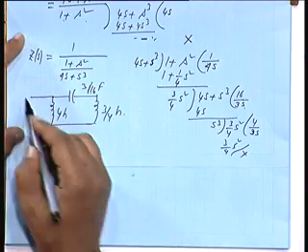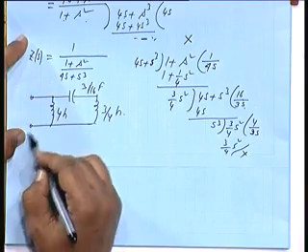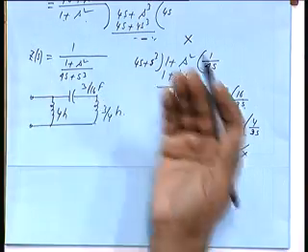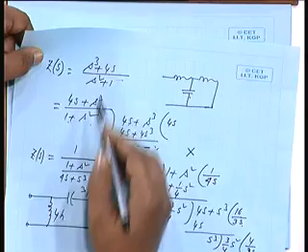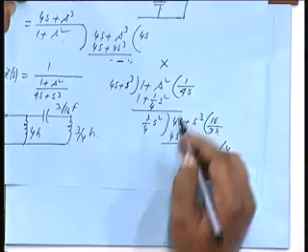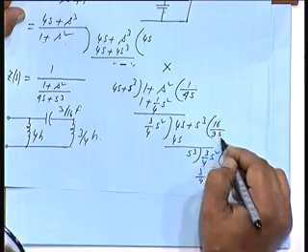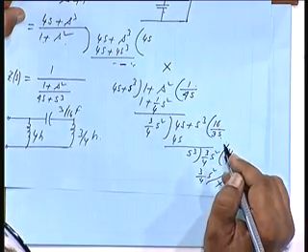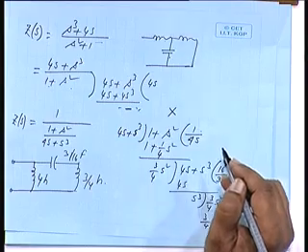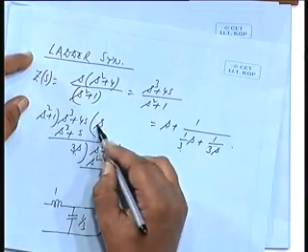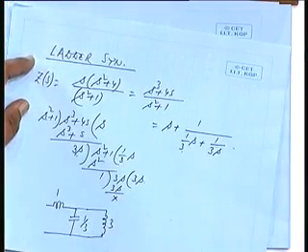Is it all right? That means, now I have another network. If I reverse the order of the polynomials, put them in ascending order, and then carry out the division such that the quotients are always multiples of 1 by S. Earlier it was coming as multiples of S. So, alternately it was inductance, capacitance and so on.